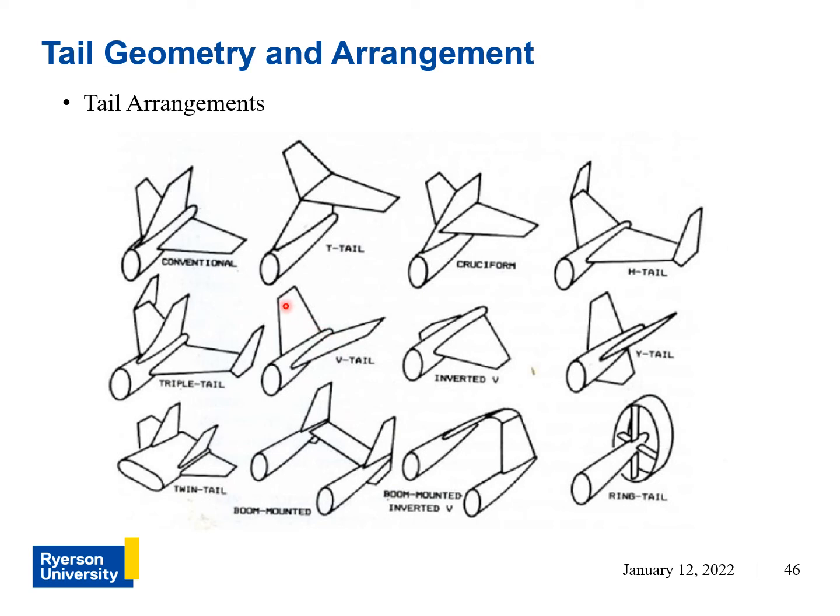And so the aerodynamics of this is basically going to have to be the same as this, except that you sort of divide the function of a vertical tail and a horizontal tail between these two surfaces. So this one surface is acting as a hybrid, and it fulfills the same role simultaneously as a horizontal surface and a vertical surface, and likewise for this one here.